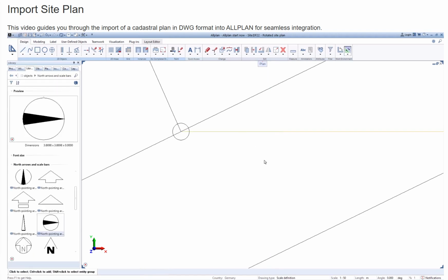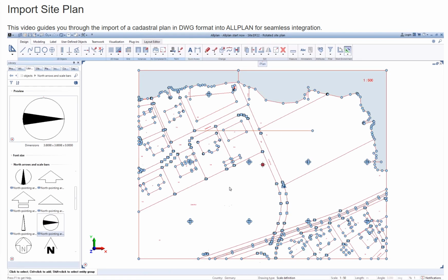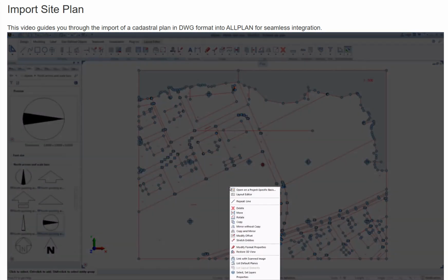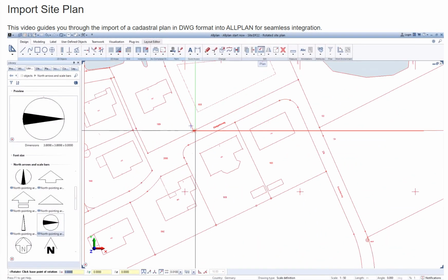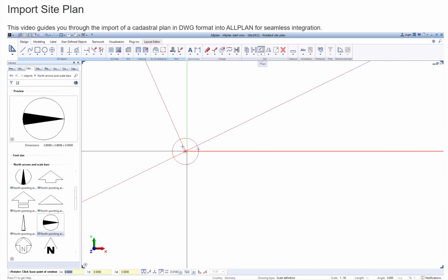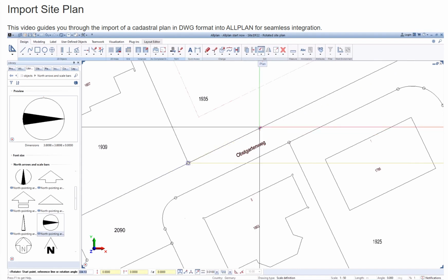With Ctrl+A or the area input, everything is marked. Now click with the right mouse button in the empty area of the drawing surface and select the command Rotate from the context menu. Now click on the starting point of the line you have just drawn as the pivot point. The lower edge of the plot is clicked as the reference line. The pre-drawn auxiliary line serves as a direction line and is clicked on.